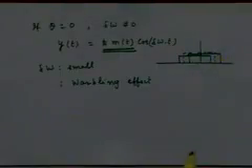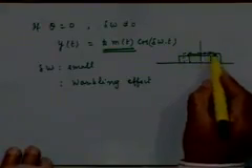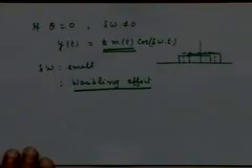It's the sum of these two spectra that you will get, right. So there is a slight frequency shift to the left as well as to the right, and what you will see is the resultant of these two. It's no longer the original spectrum. The original spectrum is this dotted line, right. That is what is happening in the frequency domain. Is that clear to everyone? So this therefore is called the wobbling effect.